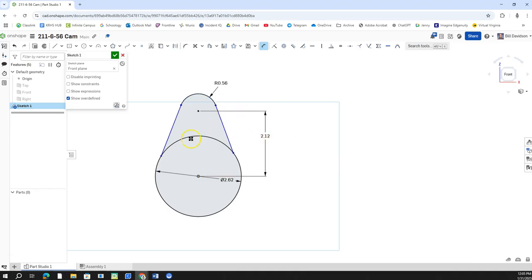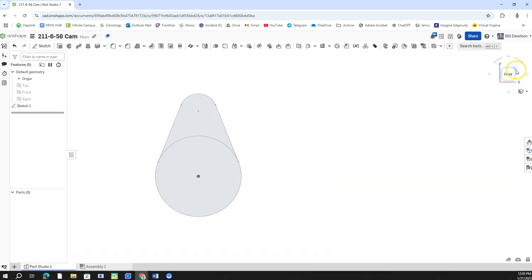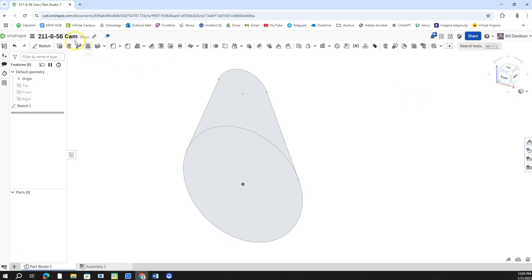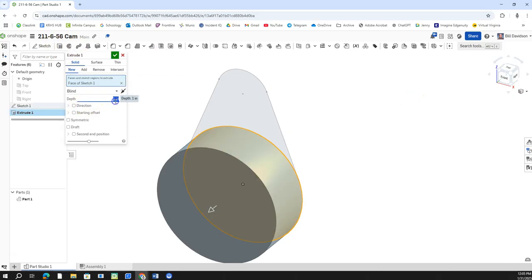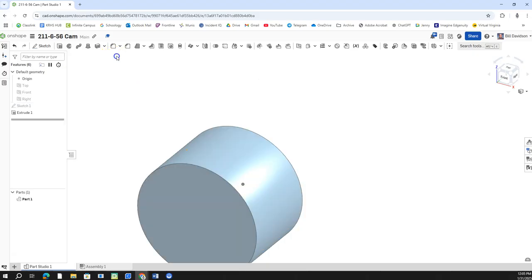All right. I didn't do the tangents on the side here, so let me do that real quick. Tangent here. I hope you did it already. That's good. If you didn't, do it now. All right. I'm going to finish that sketch, and we're going to end up sharing that sketch and using it again. But for right now, I'm just going to click Extrude, and that goes out E, which was 1.75. And I'll finish that sketch.